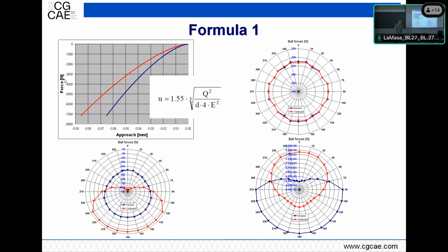And this is what is giving hard times to the rollers, because the ball is in contact, then it comes out of the contact, and then it hits again back in the contact, producing some pitting. So here what you can do is either change the load line with respect to where the load is introduced. You can move the bearings, but this is something that has huge impacts on the design, or you can increase the preload.